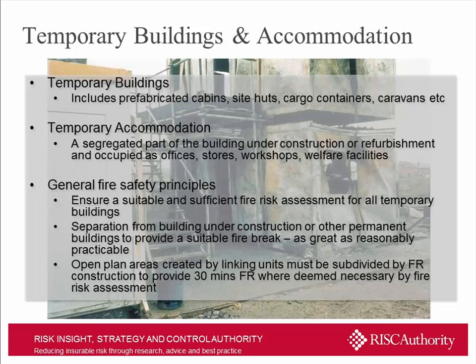But obviously, where they're going to be placed outside of the building under construction, which is a far more appropriate solution, there's a need to keep them at a safe distance. And again, if that can't be achieved, then a requirement for them to have an element of fire resistance, so as to ensure that if there is a fire, there's plenty of time to tackle it before the potential for that fire to spread to the building under construction is achieved.